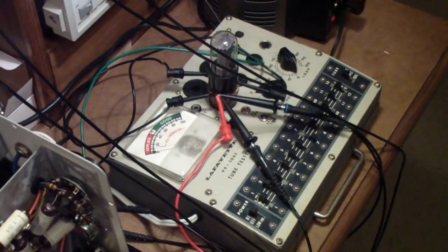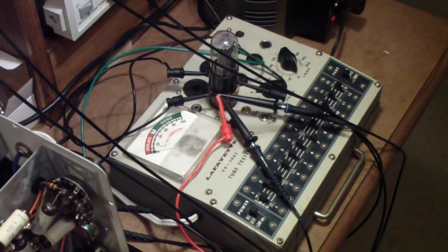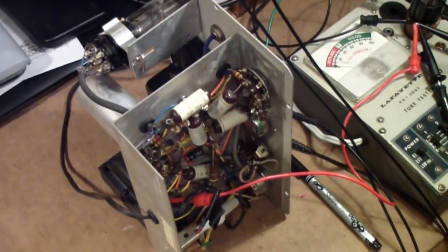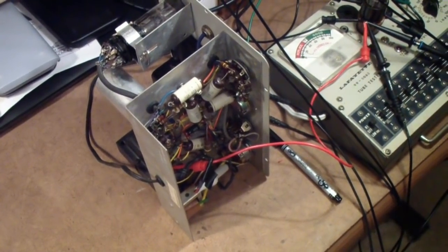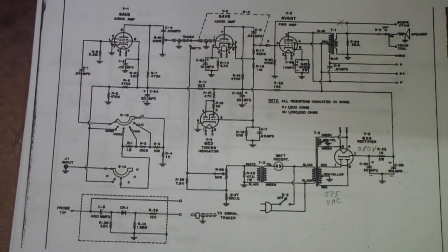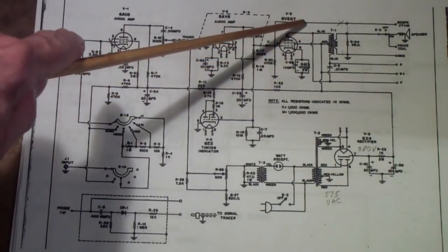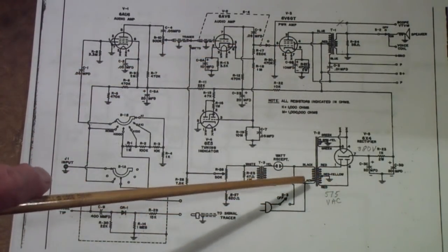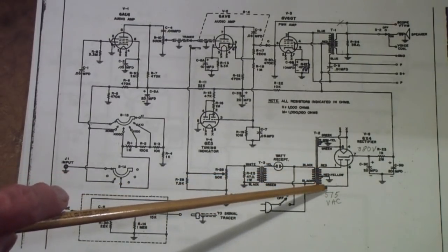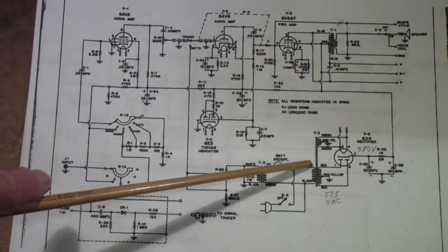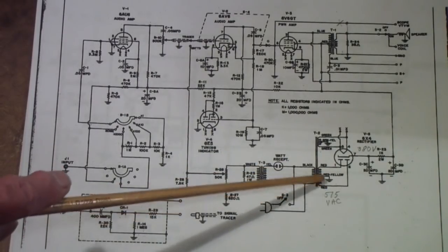And so then the next question is, where do you get the voltages that you require to that center tap transformer? Well, I got that off a Knight signal tracer. And let me show you the schematic of that. Here's the schematic of the signal tracer that I used. And primarily all I'm using it for is for the purpose of taking advantage of this center tap transformer that will provide 575 volts AC center tapped.